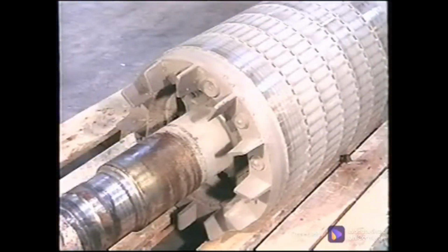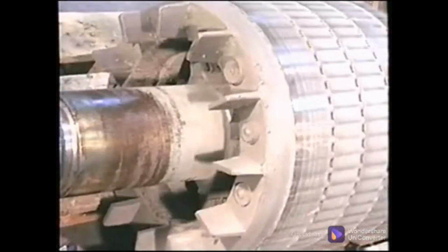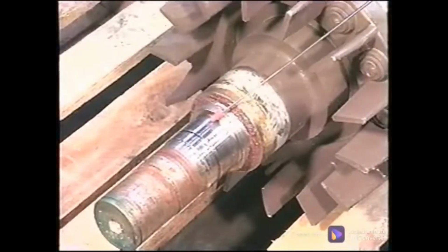The end ring can develop defects such as cracks, since the current moves along a rotor bar to the end ring and then along the end ring to a rotor bar on the other side of the rotor. Cracks cause increased resistance to current flow. Excessive heat is generated with any open or high-resistance spot, and when these are on the end rings, the heat tends to cause the rotor to expand axially as well as radially, exerting force against the bearings, accelerating bearing degradation.